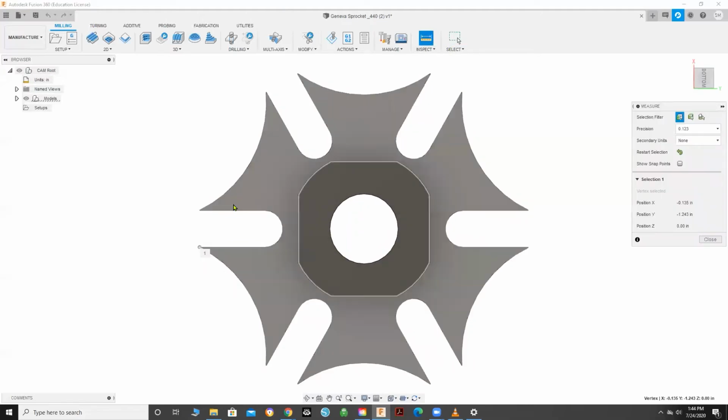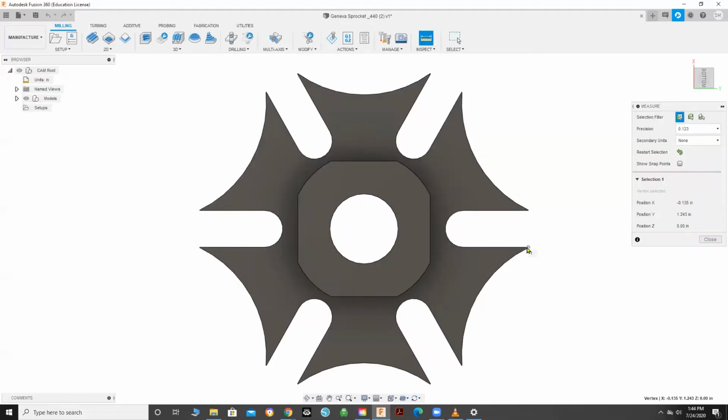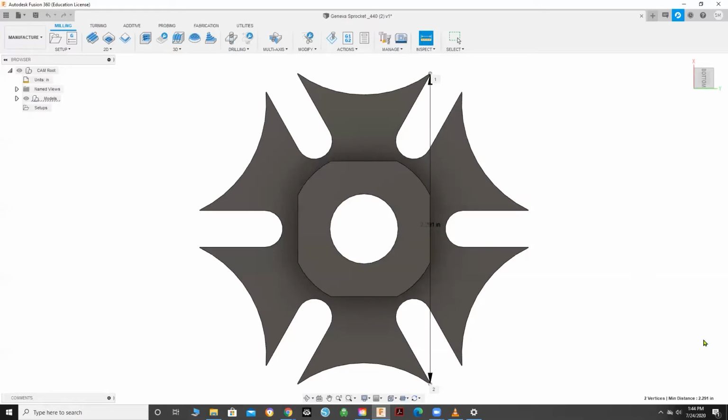If you do not know which side is your long side of your model, you can use the inspection tool to obtain the length and height. This also comes in handy while selecting your material. The material selected must be larger than your model on every axis.